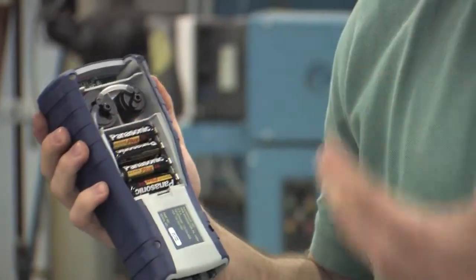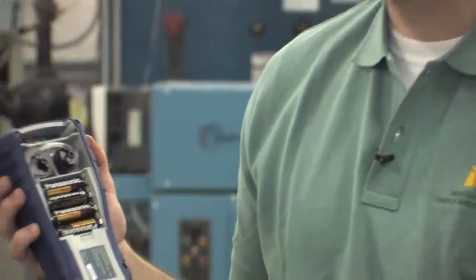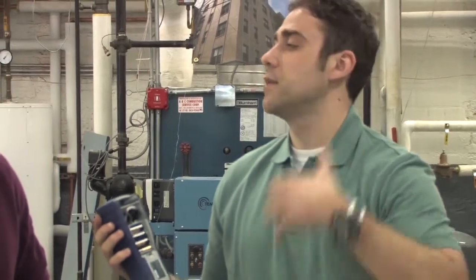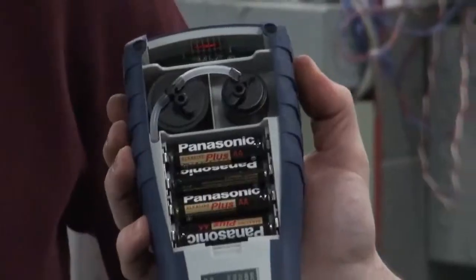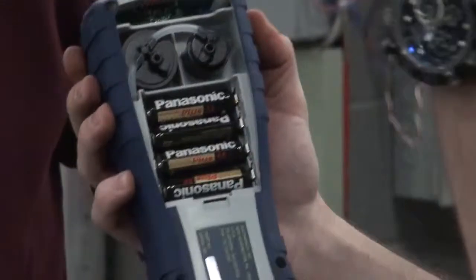So what we're going to do is measure the amount of oxygen left over inside the combustion gases. So whatever is going up the flue pipe, we'll measure the oxygen. There's an algorithm built into this analyzer. And once we have the oxygen number that's left over, we can calculate the rest. We can calculate the carbon dioxide content. We can calculate the carbon monoxide. And by the temperature of the flue gases, we can see how efficient we were.